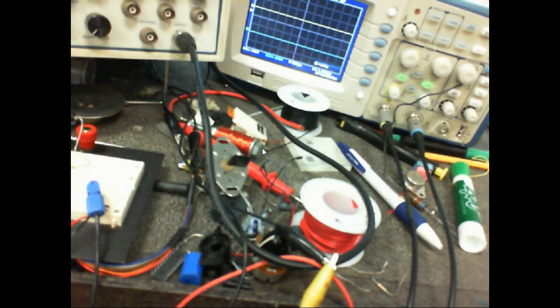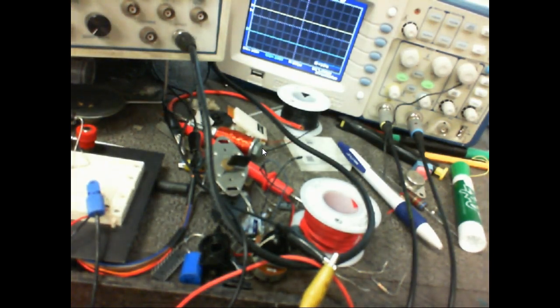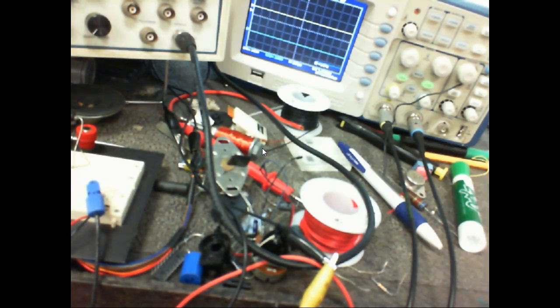We have several methods to develop a touch screen. We can use what they call a resistive touch screen, which basically has 2 plates together, and when you press them, you change the resistance. Those are really nice because you have to press on them harder. You'll run into these in manufacturing because it's a very harsh environment. Most of the HMI panels in industry use a variable resistive touchscreen. What's nice is you can have gloves on and push on them, or hit them with your fingers.